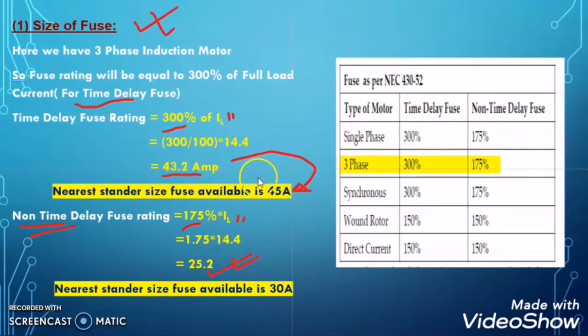The nearest available fuse for the time delay type is 45 ampere, and for the non-time delay fuse, the nearest standard size available is 30 ampere. Here I want to highlight one more point. This multiplication, that is 300% and 175%, is valid for a 3-phase motor.